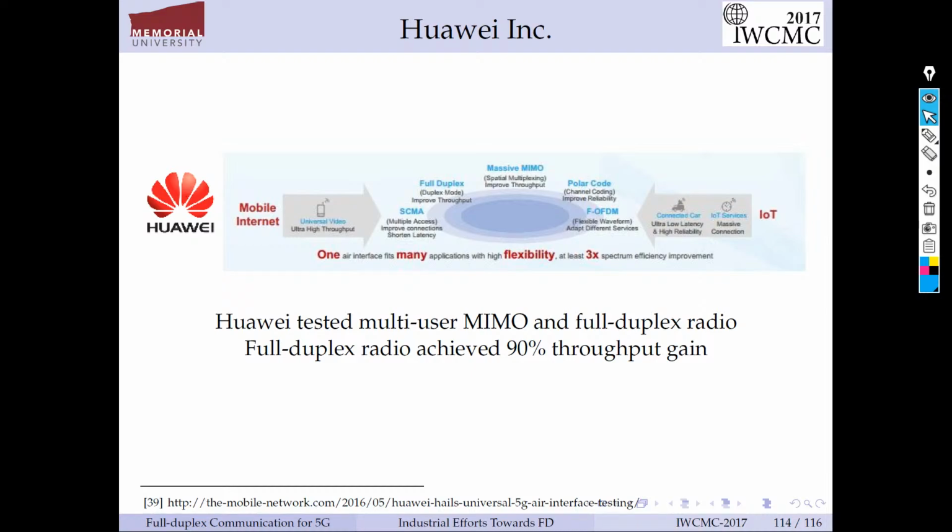Maybe it's going to be limited just to the downlink, where you can serve multiple users. In the uplink, transmitting and receiving from the user equipment, if you want the user equipment to have the in-band full duplex characteristics, you need to redesign the smartphone.